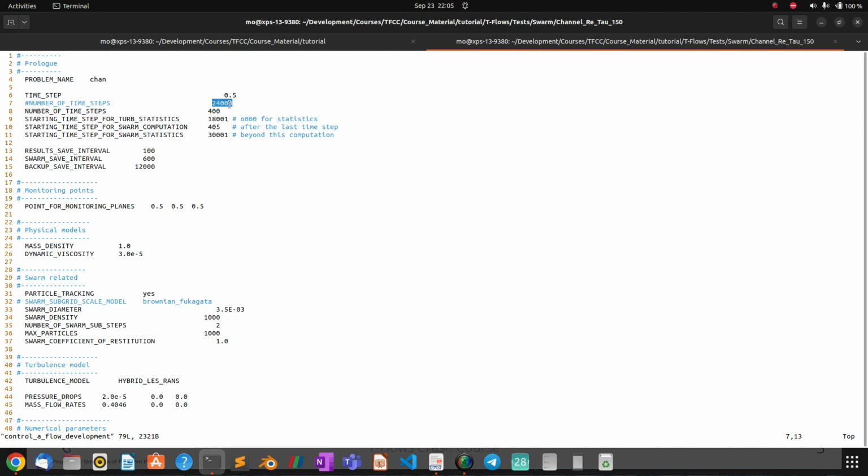Then you will need the flow to reach a steady or statistically stationary state, which is a fully developed flow, and then you need to run more or less this number of time steps. You can also check for yourself if you need more or less, but from the past I found that the convergence history will follow something between these lines.